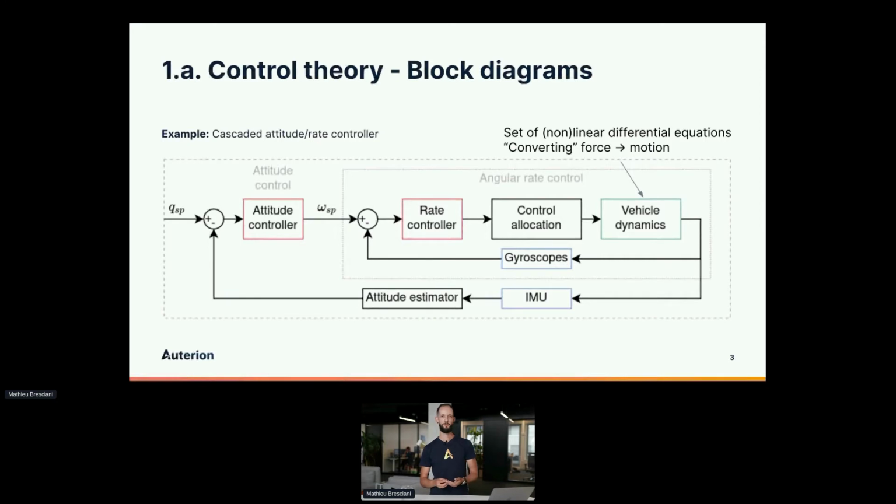And we need to tune those. So those controllers have some parameter inside, and you need to tune them for each drone you have. So it will be different if you have a large drone, which is a multi-copter, a large one, a small one, or if you have a fixed wing. The structure is the same, but the parameters that are inside are different. So we have to find them.